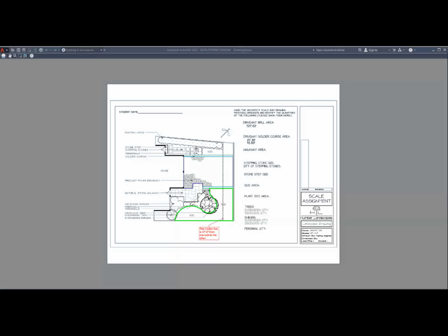When you do send me this particular drawing, you'll notice I can see your polylines in each of the areas. The mulch area or the planting bed area, you do not have to calculate dimension of any of the stock that is going through the mulch, but what you will have to calculate is the planting area that's just beside the word sod, all the way to the stepping stone and in around the entire property. You don't have to subtract, obviously, the hedge or the plants, but you will have to subtract the stepping stones that are embedded on the mulch area.